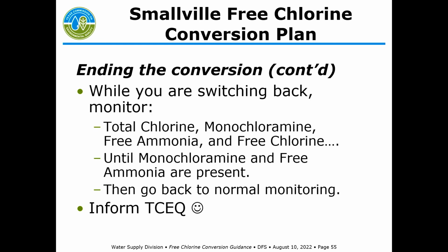Also, in ending the conversion, I mentioned this already, but just reiterating, you've got to monitor all 4 parameters until monochloramine and free ammonia are present. Then you go back to your normal chloramine monitoring at that point. And then let us know that you finished.